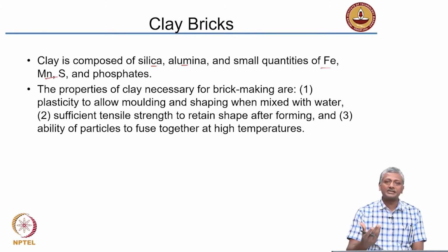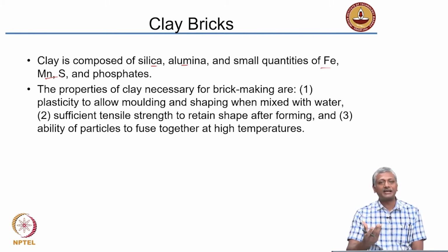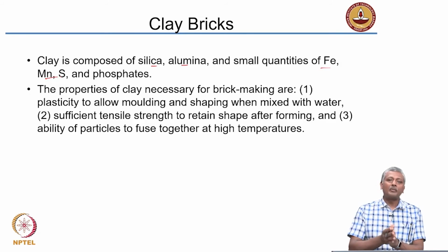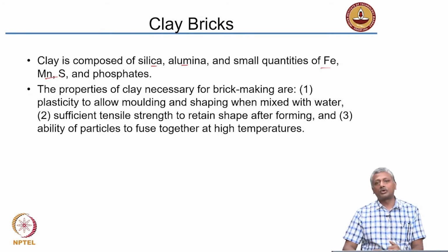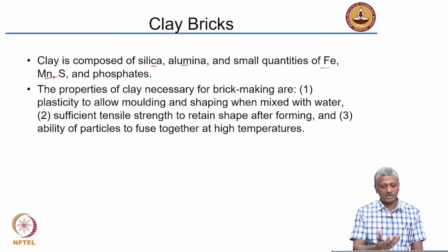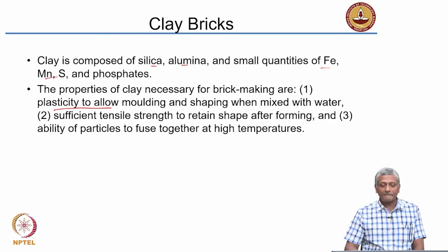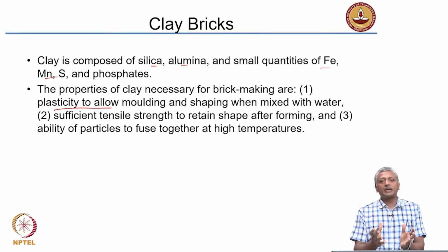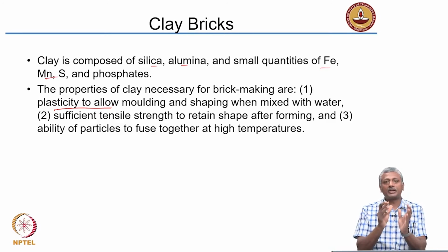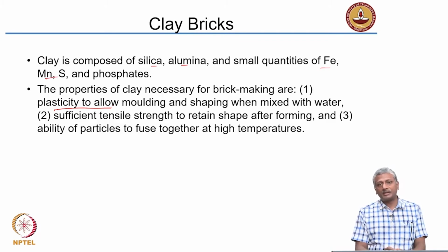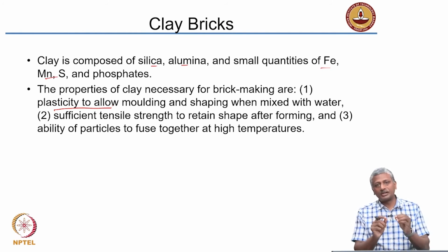Now, what do we do with this clay? As you all know, you played with clay as children. When you mix it with water, it has a nice pliability or plasticity. So you can actually start forming shapes when you mix the clay with water. So what you need is that plasticity that allows molding, and you need to have the retention capacity of a shape. Supposing you have molded a particular shape, the clay should retain that shape after mixing with the water. So your water content should be just enough so that the clay is able to retain its shape.